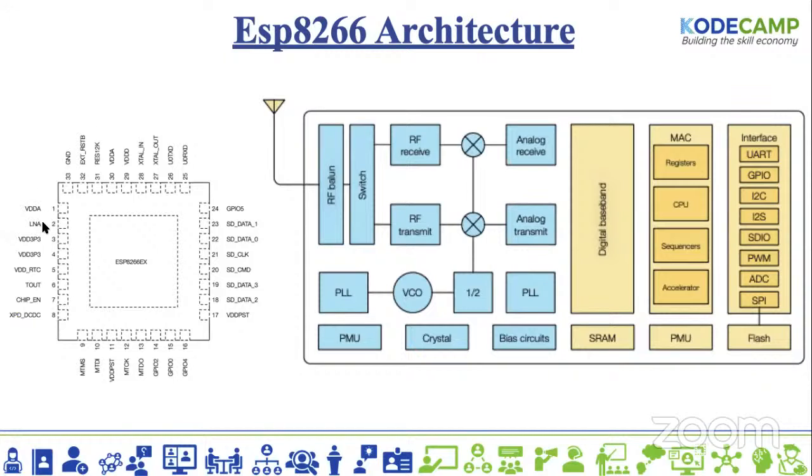It makes use of this RF antenna interface, which uses the chip on board having an impedance of about 39 plus j6 or around that. It's kind of an L-type or pi-type matching network to match the specific antenna you use.